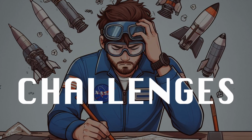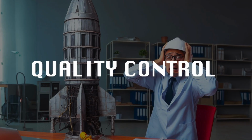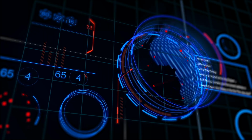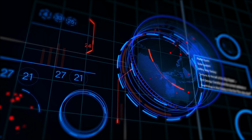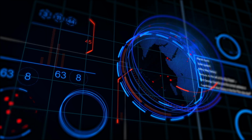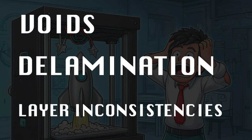This brings me to the challenges of 3D digital design in aerospace. The first one is quality control. Quality control in 3D digital design is a demanding process, which focuses on ensuring the end product aligns with the specified standards. Meticulous attention is needed during 3D printing, as this technology can introduce defects like voids, delamination, and layer inconsistencies, which may jeopardize the structural integrity.